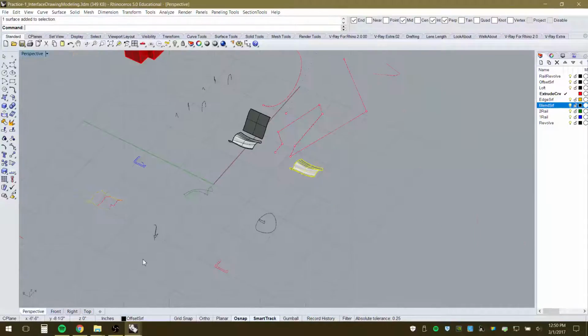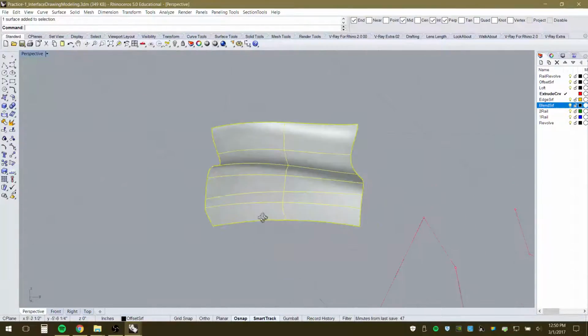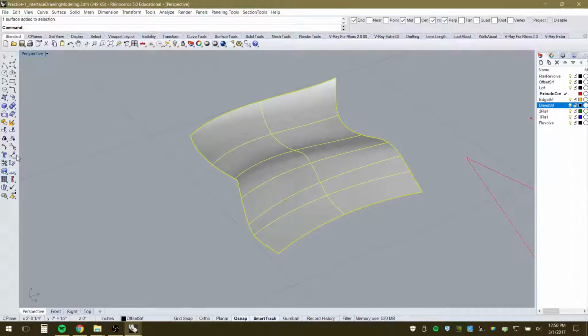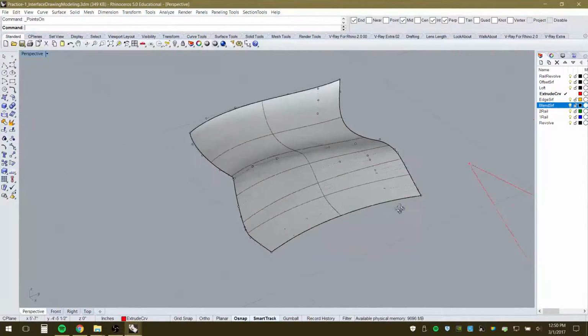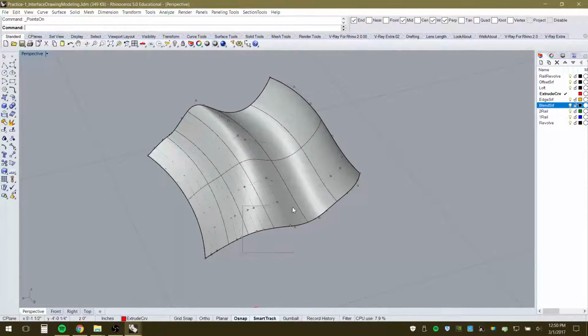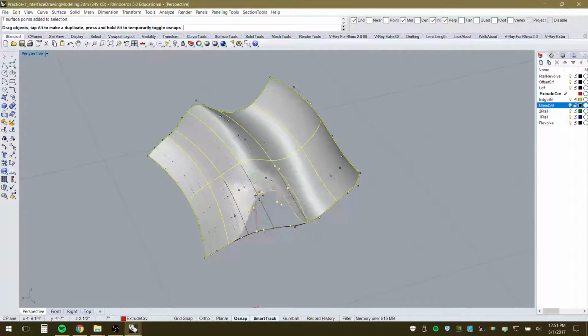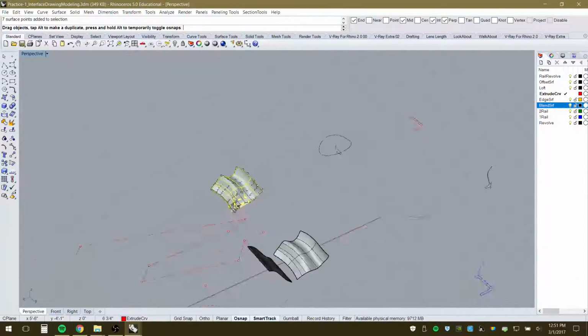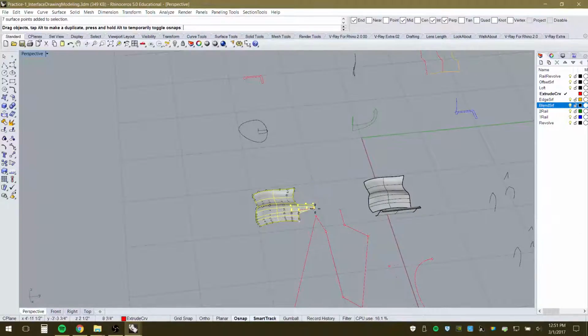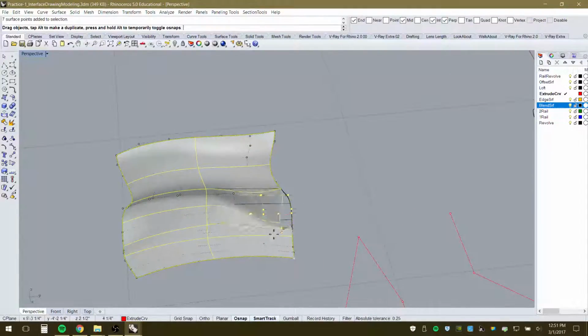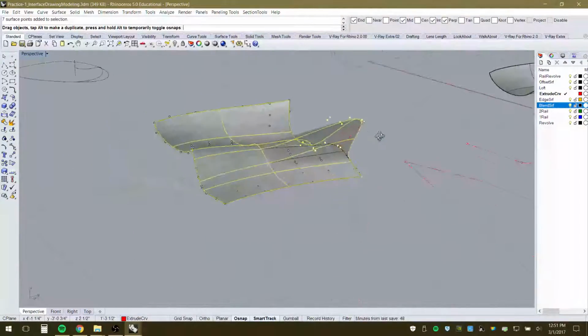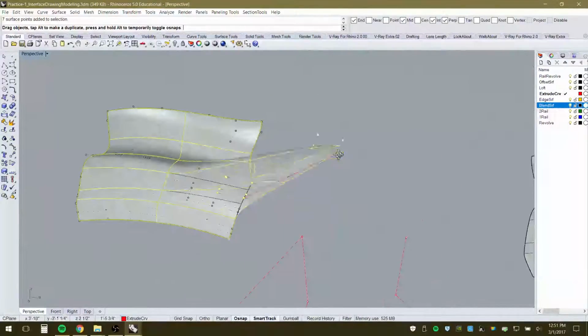So if I go into perspective view, I can also turn on control points here again, either F10 or you can use this tool here. It has certain control points here, and I can window select some of these or just point select one of these, and I can start distorting that image one way or the other. Now I'm holding down my left button here on the mouse, but I can still use my right to orbit and navigate around a little bit. So that's nice to know.